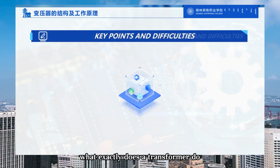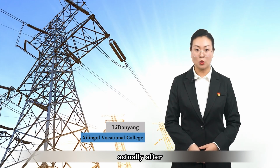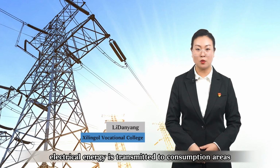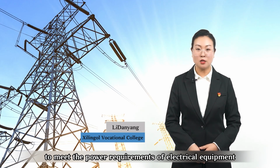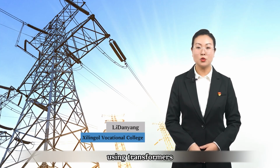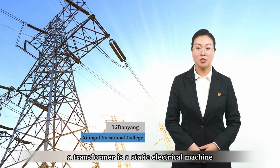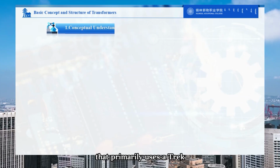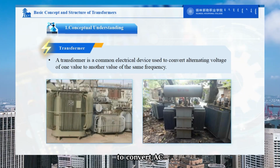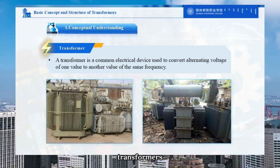What exactly does a transformer do? Students, have you learned about the basic structure of transformers actually? After electrical energy is transmitted to consumption areas to meet the power requirements of electrical equipment, it needs to go through various substation levels using transformers to reduce voltage to the values required by various electrical devices. A transformer is a static electrical machine that primarily uses electromagnetic induction principles to convert AC electrical energy of one voltage and current into electrical energy of another voltage and current at the same frequency. In other words, transformers enable the conversion of electrical energy between different levels.